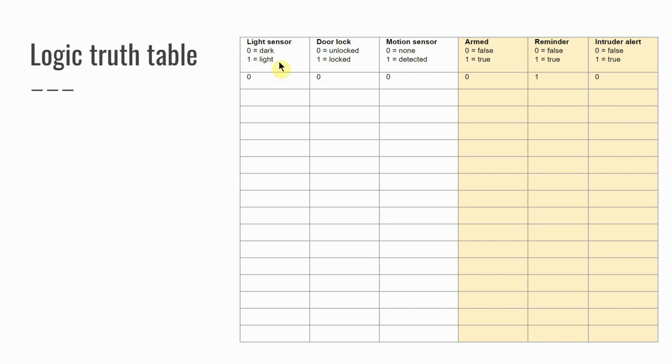You need to identify the logic levels for each one of these sensors. So I've said that the light sensor would be 0 when it's dark and 1 when it's light. Notice that's digital. I'm not using an analog sensor here, which would need a little bit of additional circuitry. But if it's an A-level project, you could just use a switch, and you just flick the switch, and the switch just suggests to the system whether it's light or dark conditions. Anyway, so yeah, you fill out this.